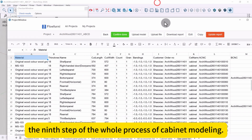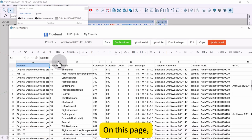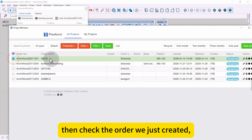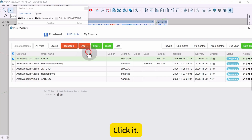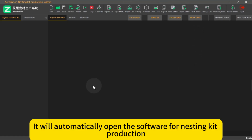The ninth step of the whole process of cabinet modeling is the production of wood and nesting sets. On this page, we can click on all orders. Then check the order we just created. And then, in the other cutting options, find the option for nesting kit production. Click it. At this time, it will automatically open the software for nesting kit production.